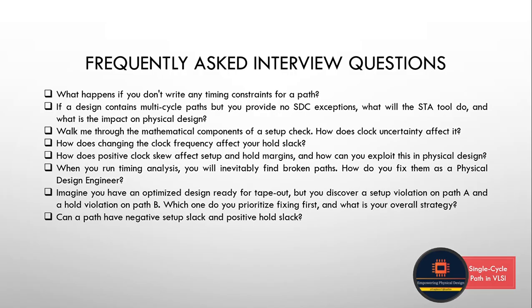Positive clock skew delays the arrival of the clock at the capture flop, which improves the setup margin by giving data more time to arrive. But it worsens the hold margin by requiring data to remain stable longer. So clock skew will sometimes benefit setup, but it won't benefit hold. Vice versa, it will also happen.